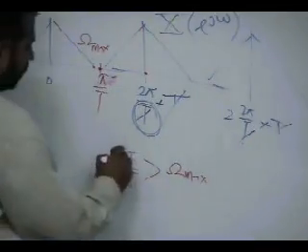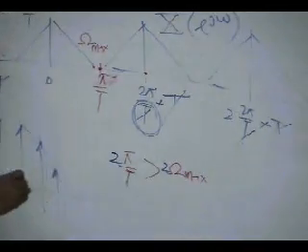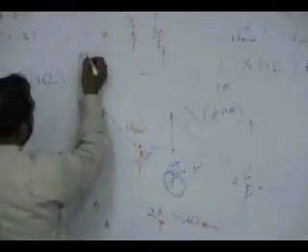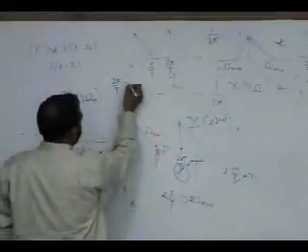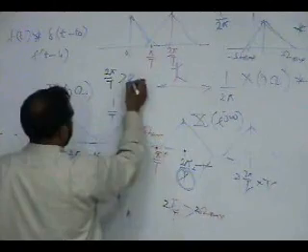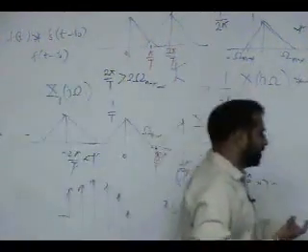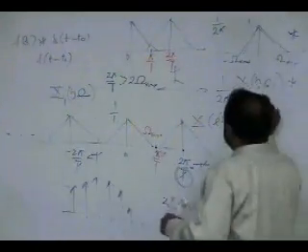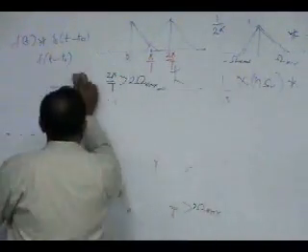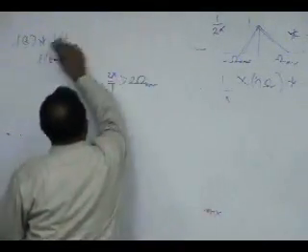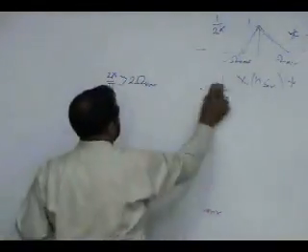If I multiply it by 2 and 2, just to make this the sampling frequency, so I say 2 pi by capital T must be greater than twice the highest frequency. Okay, this gives us a rule. So the modeling is done to get to this rule, which says your sampling frequency must be greater than twice the highest frequency.